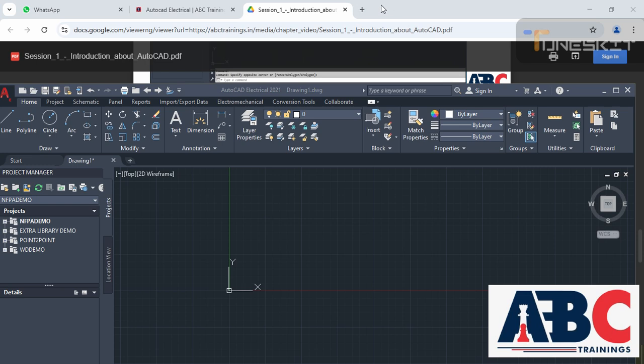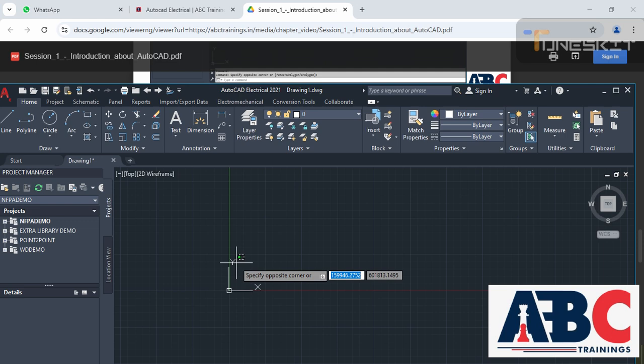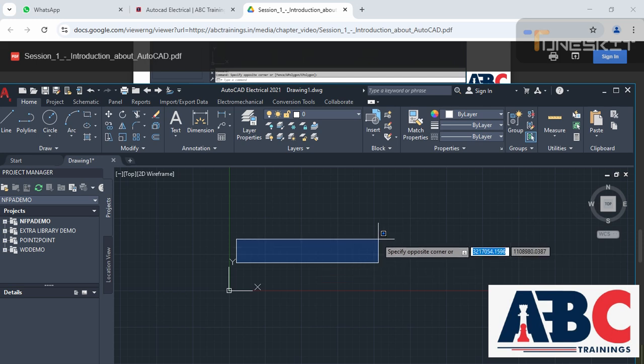In AutoCAD, a coordinate system is a reference framework used to define the location of points in a drawing. Look at the cursor: the X and Y are the points of the drawing, primarily using the Cartesian XYZ system, where the world coordinate system WCS is a fixed origin point, and the user coordinate system UCS allows you to dynamically adjust the working plane. It means you can adjust the plane, the workspace, through the XYZ point coordinates.